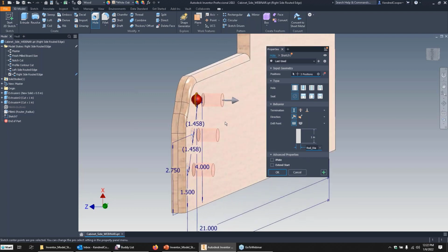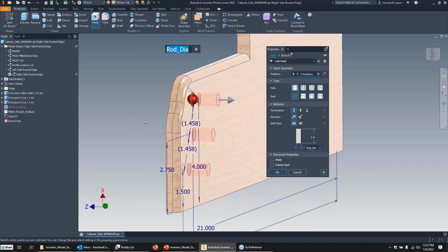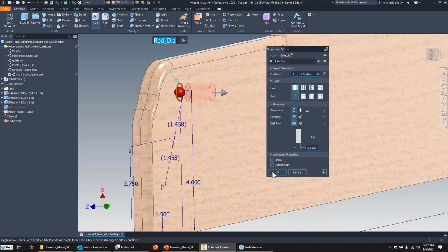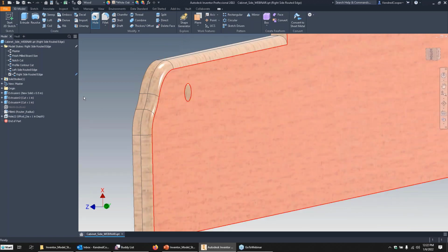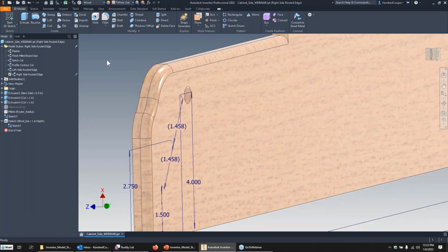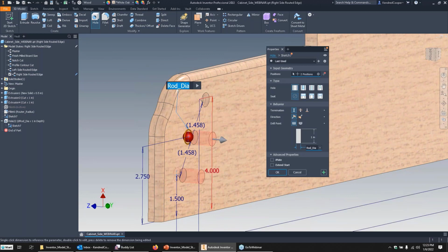So for this to work out the way I need, I'm going to have 6 drilled hole features to get all the combinations I want. For this, I'm just going to deselect the ones that I don't need right now, starting with the top one, assigning it to the appropriate diameter. And then I'm just going to share that sketch to make it available and continue on making 5 subsequent drilled hole features. Picked the wrong thing. So there's another one, the third one.